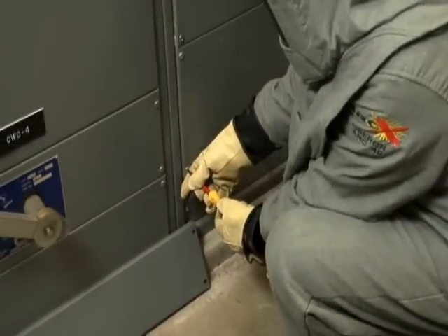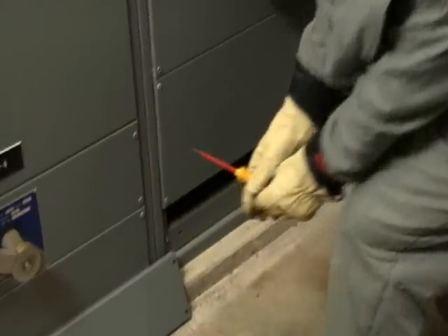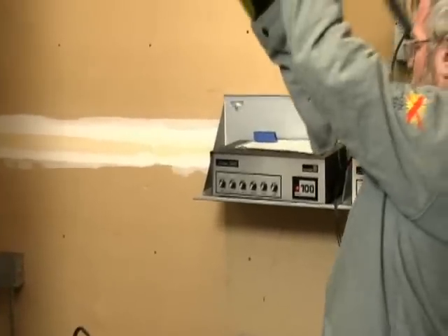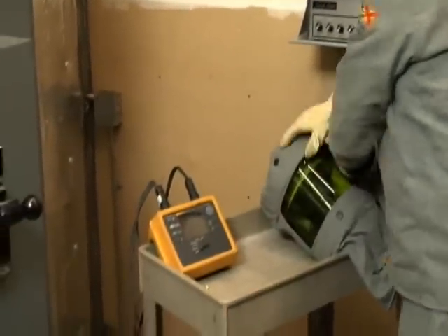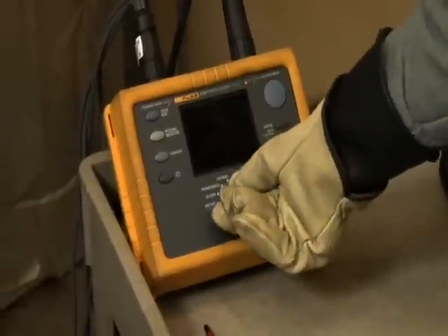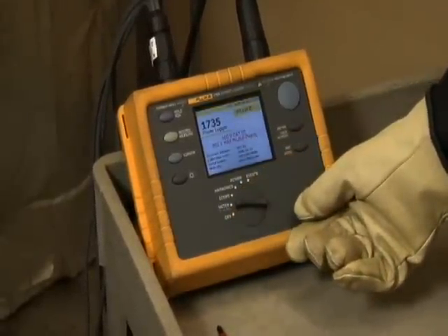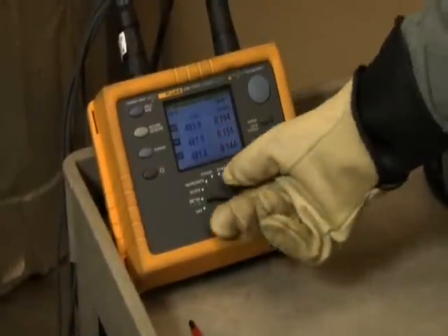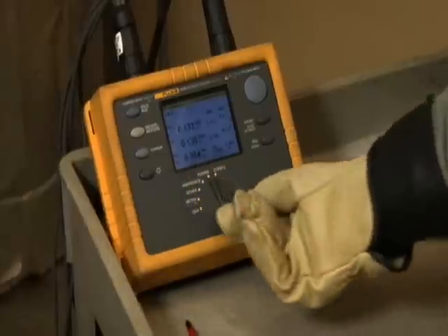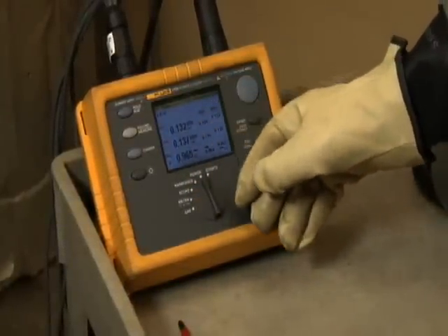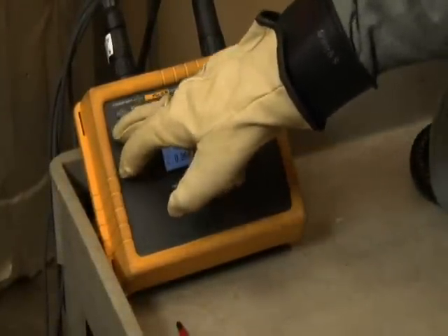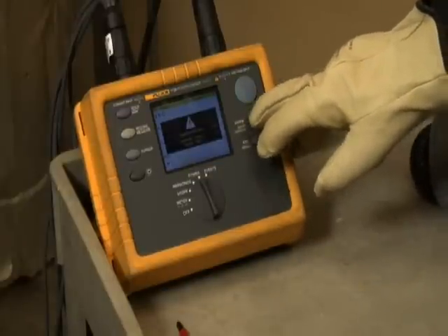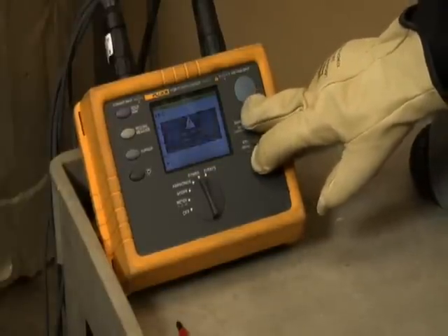Once you've completed your connections, always make sure to check your setup and verify that connections are correctly made. When you're preparing to leave a logger behind for an extended time period, you want to make sure you're capturing the correct data. You can check this by turning the dial on the Fluke 1735 Power Logger to meter. The Fluke 1735 Power Logger automatically captures all of the major power parameters while it logs. In this case, we care mostly about kW, kWh, peak demand, and power factor. It's managing these values that will save you money.